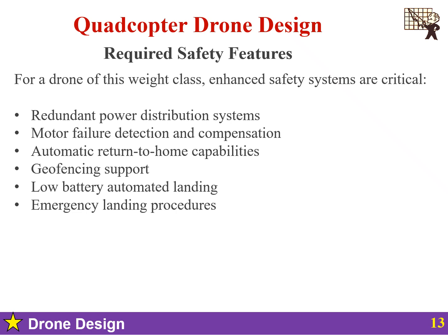The next is position lighting required for visibility and orientation. FAA compliant anti-collision strobes, orientation lights that is the red starboard, green port and white aft. Higher intensity LEDs visible to 5 plus kilometers.